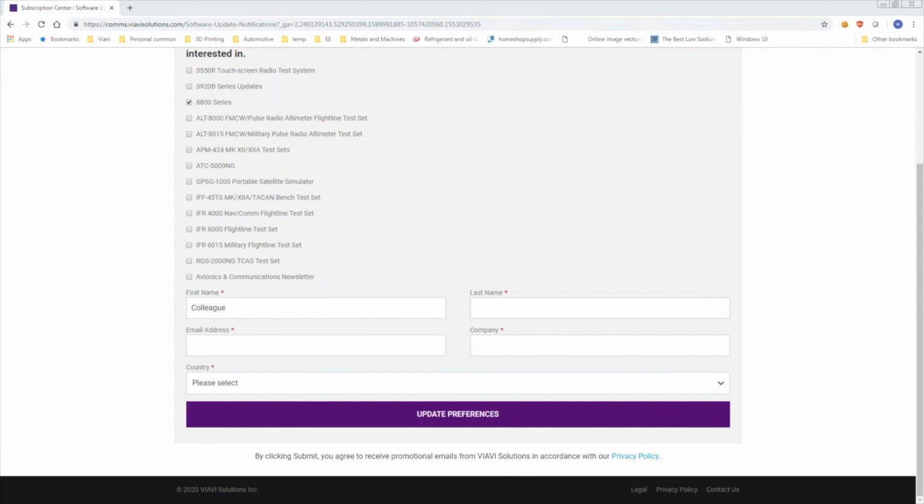And for what we're doing, the loss imparted by your connectors should not affect the results enough to be concerned about. If you have a connector that's dropping a half dB or a 1 dB, obviously that's a concern. But if you have a connector that has those characteristics, you probably should not be using it for anything. Does that answer the question?